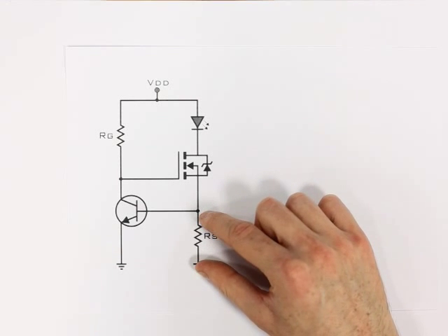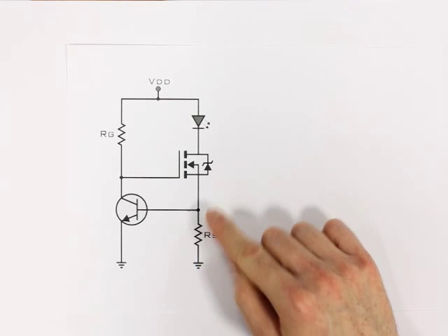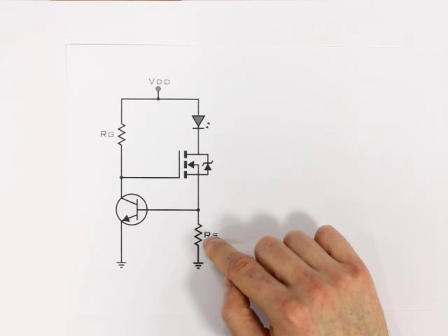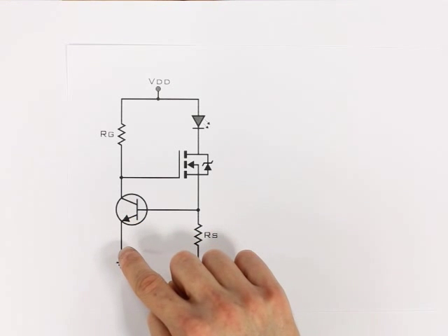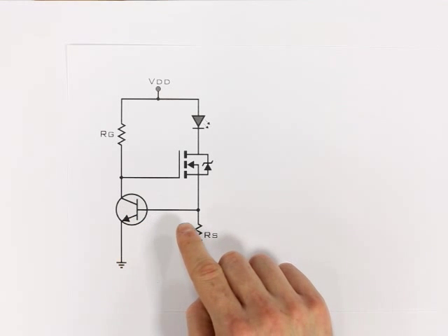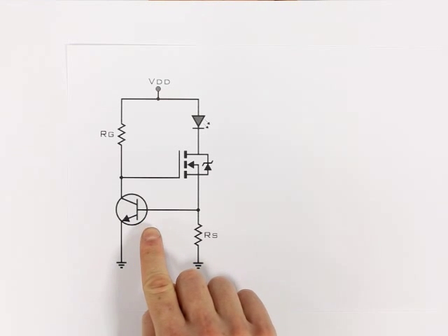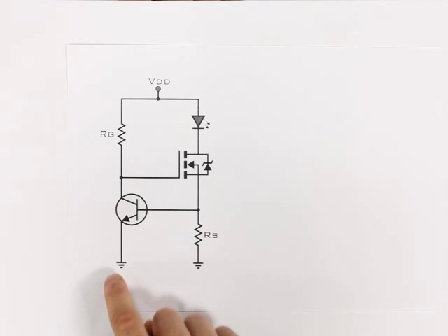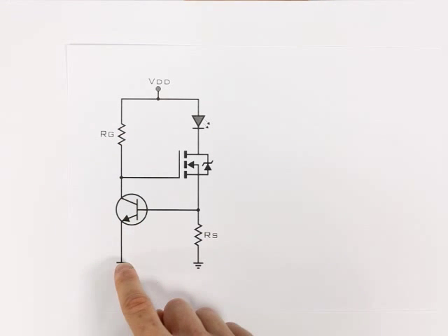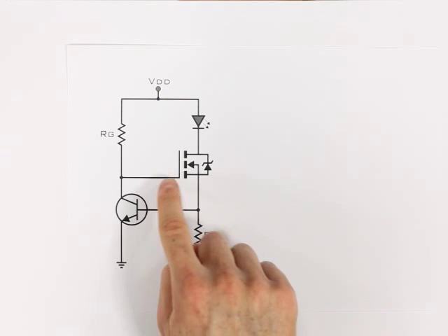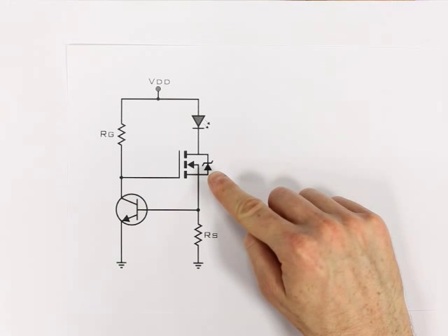So we're setting a desired current through this branch of the circuit here, just across that sense resistor. And if we're getting too much current coming through the LED, that's going to spill through the BJT. And that's where the negative feedback occurs. For just a tiny bit of base current, the BJT will allow a very large amount of collector current. And as that opens up, current flows through here, it's going to pull the gate of the MOSFET to ground, shutting off the current IDS.